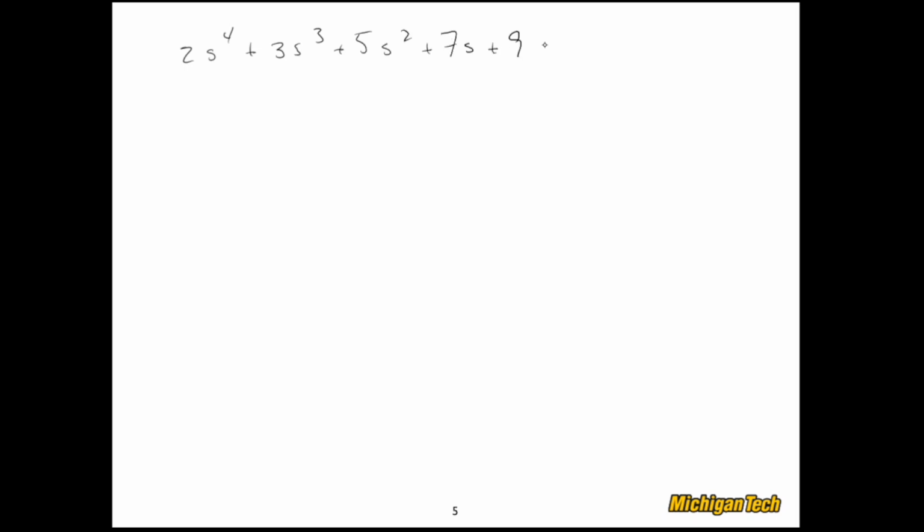And this example is kind of nice because, here I better call it f of s, because I have different coefficients for each of the terms in this polynomial so that we can keep them all straight as we go through the math. So here's my first two rows, s to the fourth, s cubed, and then I need to give myself a little bit of room, so I'll do an s squared, an s to the 1, and s to the 0. And so I fill in these two rows first.